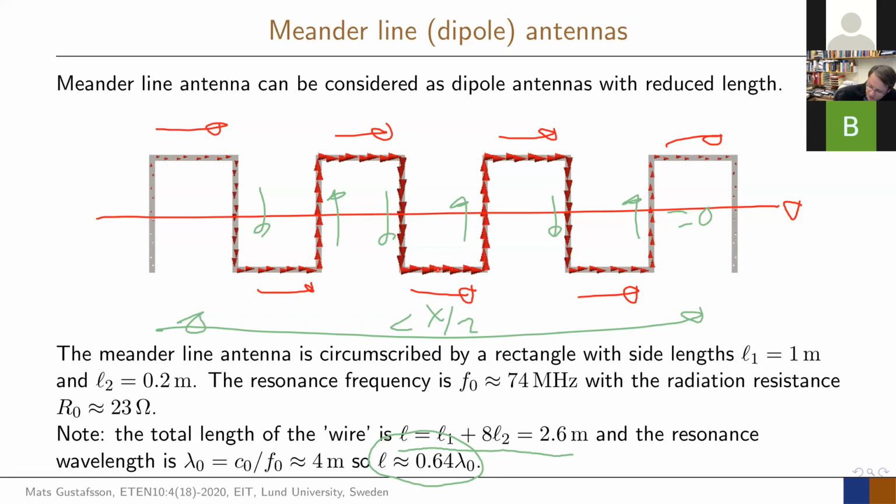The bad part with this one is what you see here. By shrinking that, it starts looking like your Hertzian dipole, because it behaves the same as your Hertzian dipole, for which you computed the radiation resistance. And if you remember, you get very low numbers on that one. This is slightly longer, so it will go up a little bit, but the general trend is there. When you make it shorter and shorter and shorter, your radiation resistance goes down.